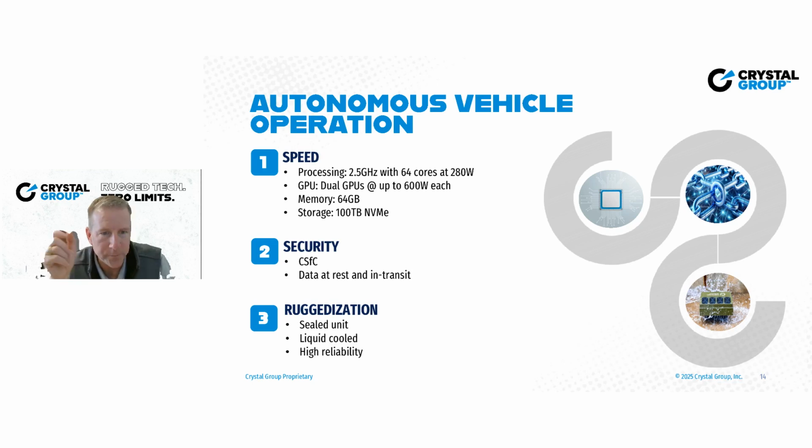And then based on the environmentals that we're talking about, I would love to say, hey, it's a sheet metal chassis, all open, no big deal. We'll put a couple of filters and it's fine. That's not really realistic. When you're talking about 2000 watts at these kinds of temps, and this kind of environment, you're really talking about a sealed unit, which means you're probably going to go liquid cooled, which also then you've got to figure out how to do that from a high reliability standpoint.